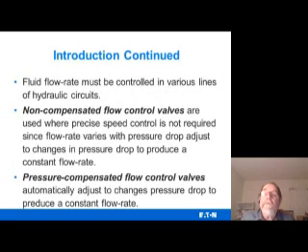Fluid flow rate must be controlled in various lines of the hydraulic circuit. Non-compensated flow control valves are used where precise speed control is not required, since flow rate varies with pressure drop. Pressure-compensated flow control valves automatically adjust to changes in pressure drop to produce a constant flow rate.